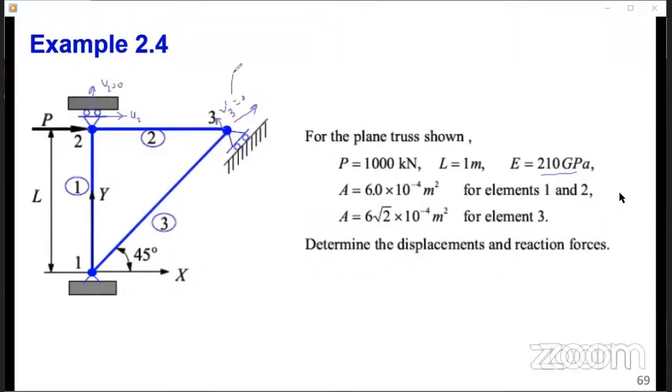Because the V at the global coordinate system is the one vertically up. And the V at the global coordinate system, V3, is in that direction. So if this is a roller support, as a result of this applied load, we expect to have a movement upwards. As the support moves upwards, we are going to have a component displacement.